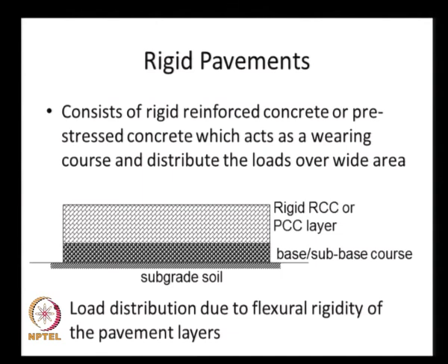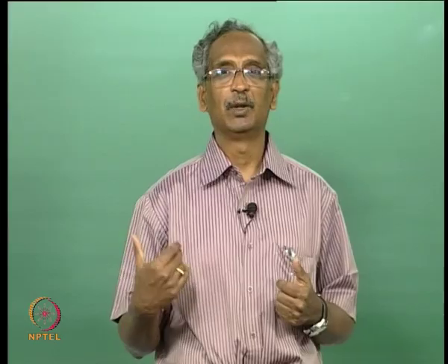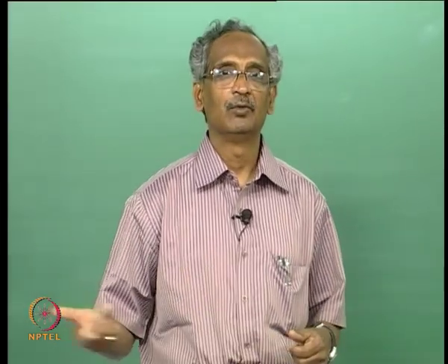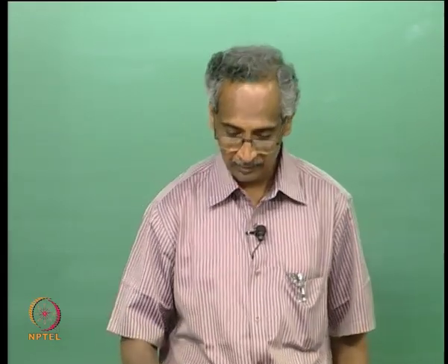And the load distribution here in the case of rigid pavements is because of the flexural rigidity of the pavement layers. So, it has a very good stiffness, so it can distribute the load over a very wide area, and the design of the thickness is a function of the structural analysis. And in this lecture or in this course, we will only look at the flexible pavements, because that is more appropriate when we are using geosynthetics.